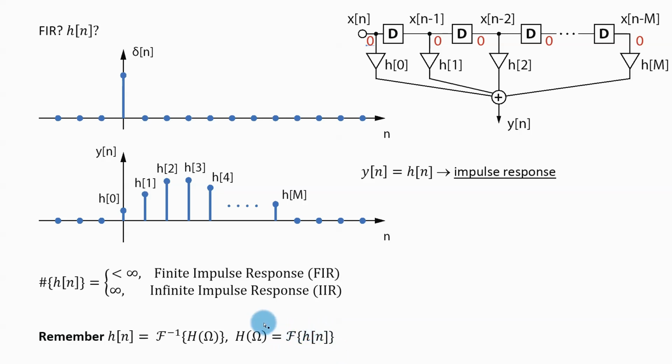the Fourier transform and tell me what its frequency response is, and from that you would be able to tell that it's a low pass filter or a high pass filter, that it, for example, can be used to suppress power noise interference. The other way around, you will come up with a frequency response, for example, one that will suppress your power noise interference, and by using this formula you can get a proper impulse response that you can use in a schematic like this to do the filtering in